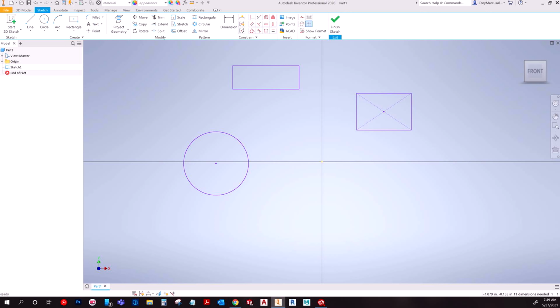So if any of y'all have taken any geometric dimensioning and tolerancing, you'll know that there's typically always a location tolerance or a size tolerance, and those are clearly a thing because location and size matter, but they're going to be what you're trying to lock in. So for instance, if I grab the circle and move it to this point and let go, it's going to imply coincident constraints, and now when I pull it doesn't move. So now it's been located.